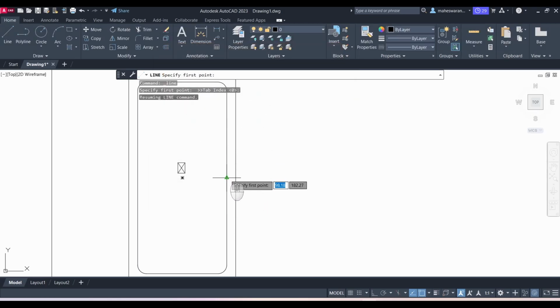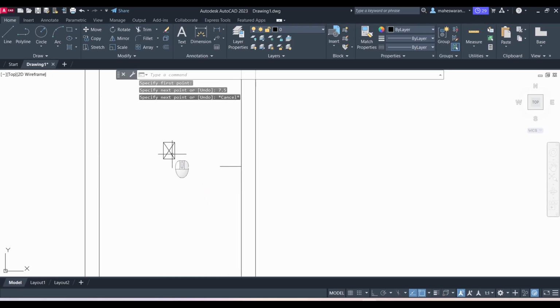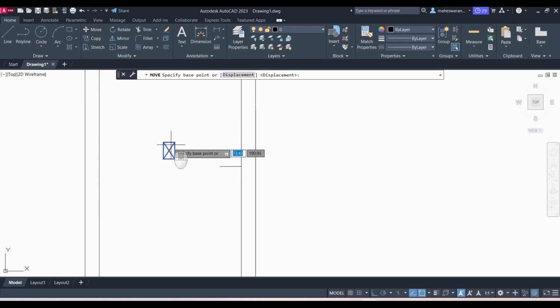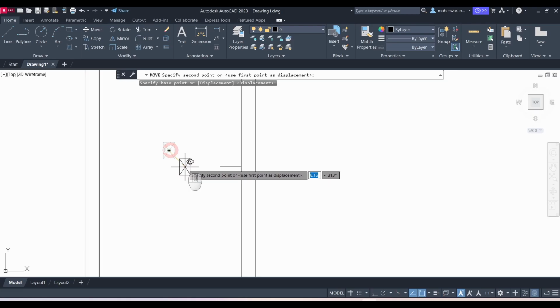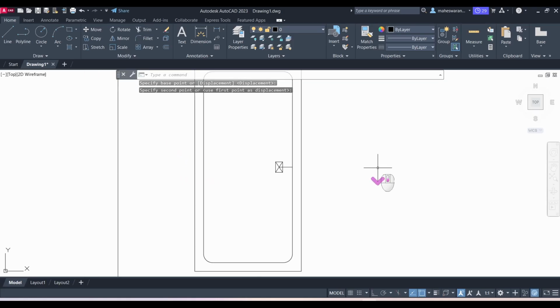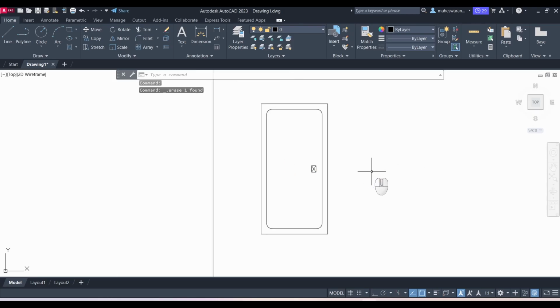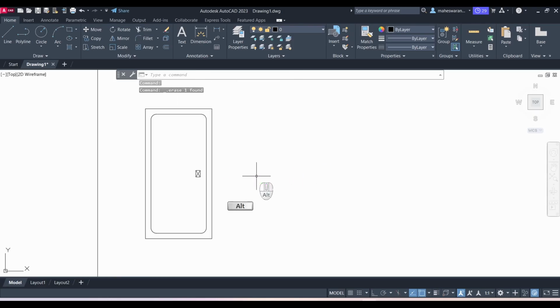So now let me move that so you get the triangle. Click once, move my cursor in that direction, enter 7.5 and press enter. So this is the point where this knob center has to be connected. So now select the knob alone. Selecting the knob. Now let me go to move command, click move command. It is asking the base point, which is the center point. So from here, move and keep it at the center of this. Okay. Now you can delete that reference line which I have drawn. Select and delete. So this completes the first diagram.